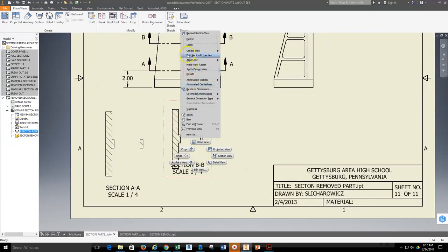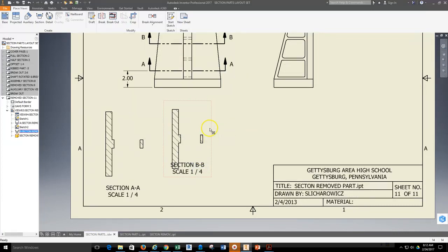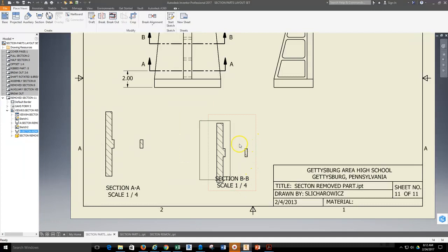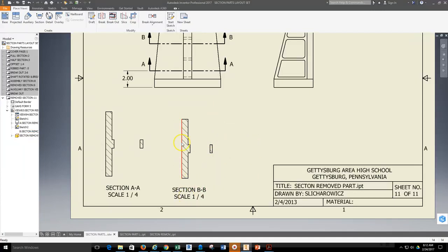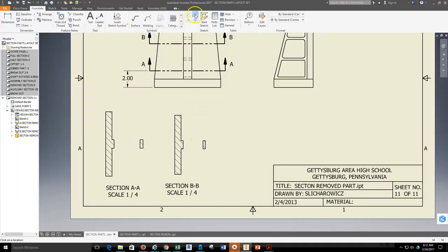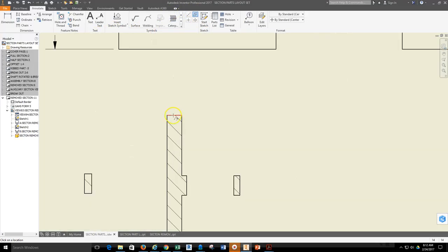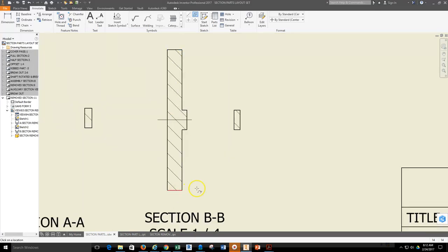I need to also now break the alignment, which looks like it's already been broken by rotating. And now I can start roughly positioning this particular view. I can also create my bisector lines on these views, so I can start aligning them by center line. So I can grab annotate, grab the bisector line tool, and then start selecting edge to edge. I should be able to then select this and pull. There we go. Pull this up off of the part.